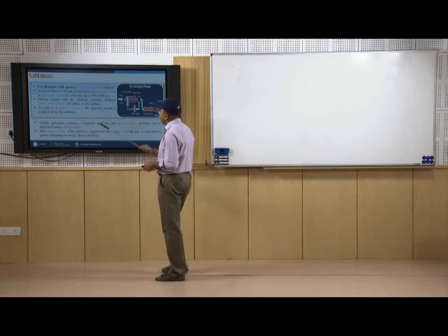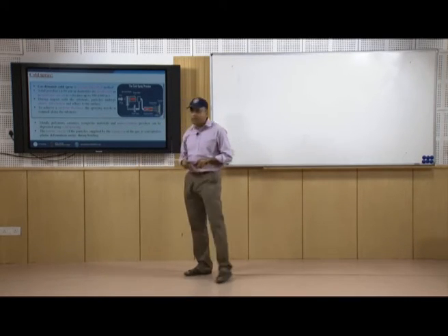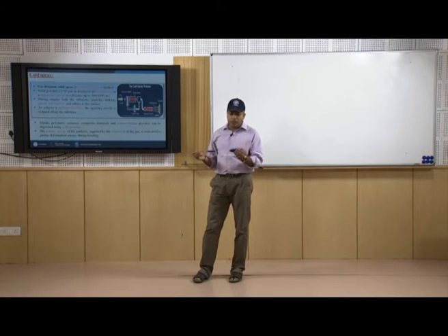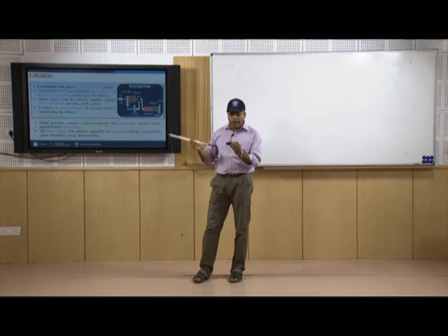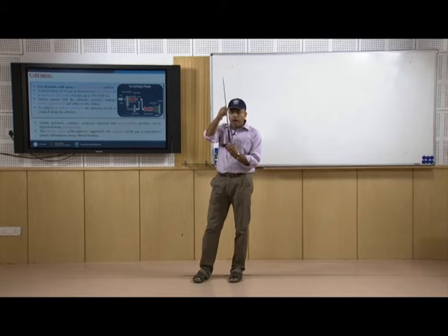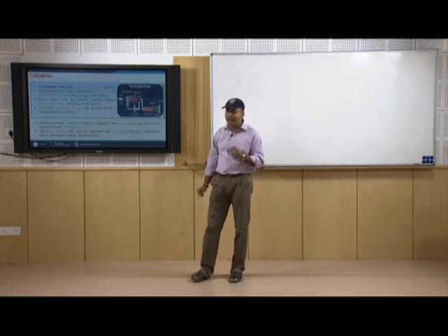To achieve a uniform thickness, the spraying nozzle is scanned along the substrate. That means, suppose this is the spraying nozzle and I want to coat this material, I have to position the substrate in such a manner that this gun or nozzle can go all around its surface so that a uniform coating thickness can be achieved.